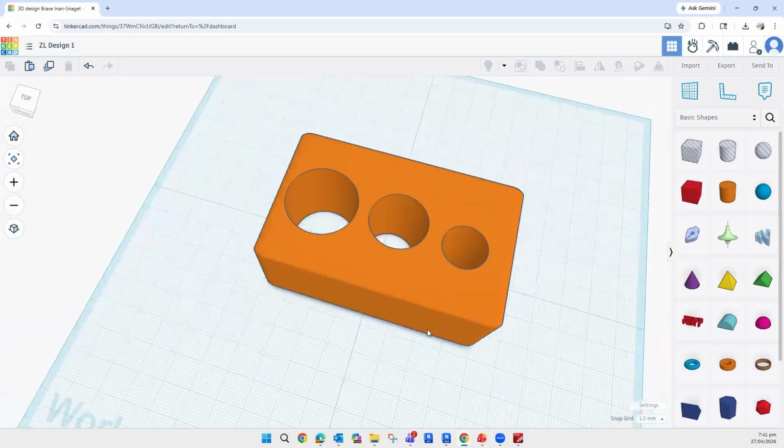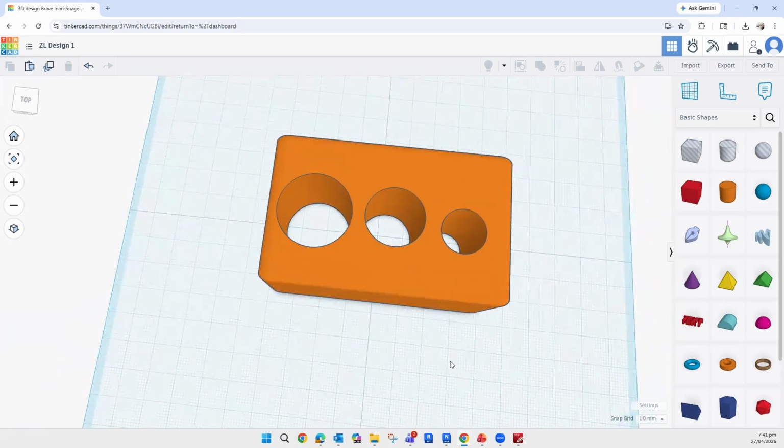That is the opening here. It goes all the way through my element. Why did it go all the way through? I never set the opening offset from my base.